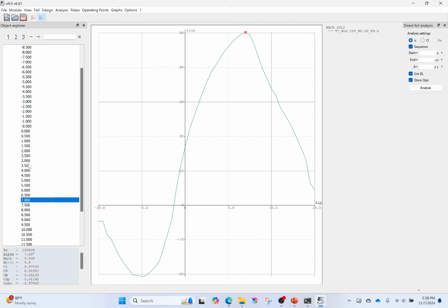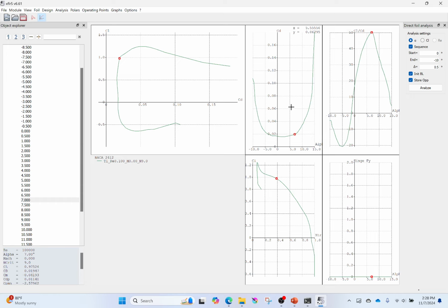And so for this particular airfoil, we would have the best fuel economy somewhere around an angle of attack of 7 degrees. And there's a lot more that goes into that. I'm oversimplifying some things, but just wanted to show you that detail. Now my question then is, well, how would all these graphs change if I add in a flap? So let's do that right now.